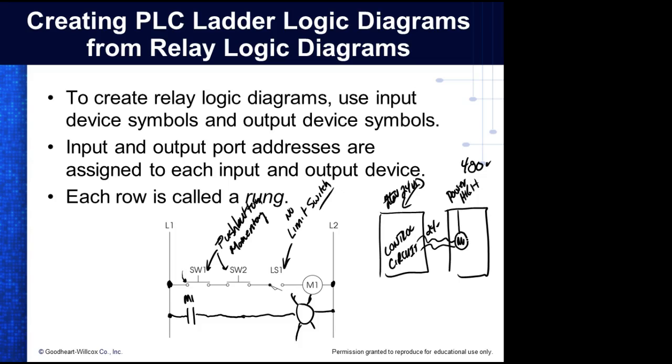But you're right, it has a lot to do with the cost, because we can use smaller components. The higher the voltage, the less current required to produce the power, right? So we can use smaller conductors, smaller size relays, and smaller coils that actually energize them. It doesn't save money on running them, because we don't pay for voltage and we don't pay for current. What do we pay for?